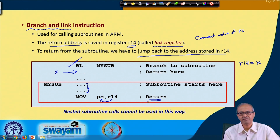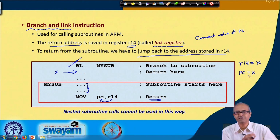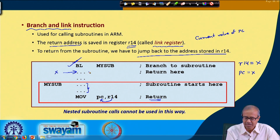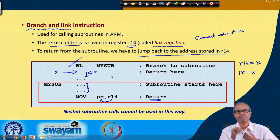So, what will happen here? This R14 contains the value of x. If you load PC with x, now PC will become x. When the next instruction is fetched, it will be fetched from this address x. So, essentially you are branching back, or jumping back, to this location and resuming execution from here. This is how you implement subroutine call and return in ARM.